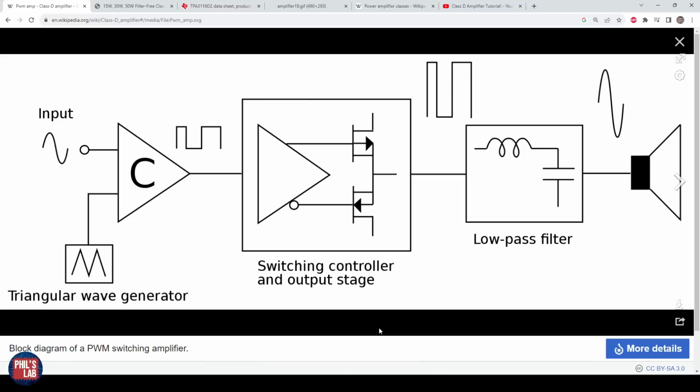A downside, especially in the audiophile community, why people might disregard Class D amplifiers, is that they are fundamentally switching amplifiers. Switching amplifiers can introduce unwanted harmonics, distortion, noise, and so on, and of course that might not be a good thing in audio. However, these days modern Class D amplifiers are very respectable with low THD and low noise values, so they can be a sensible choice in many applications.